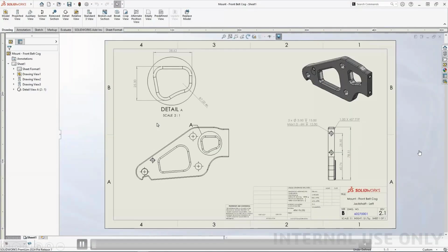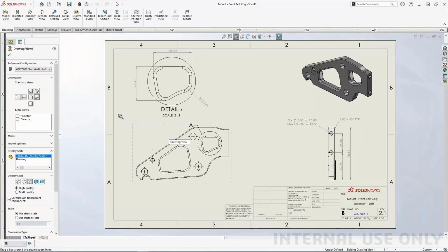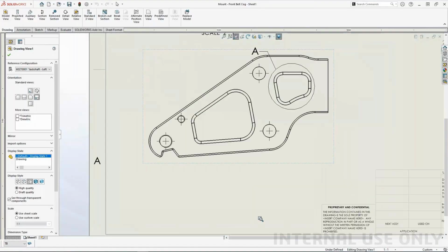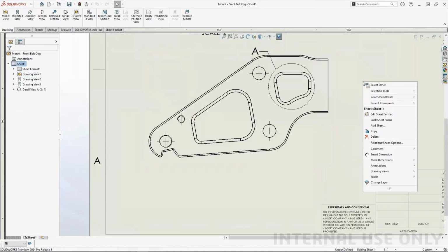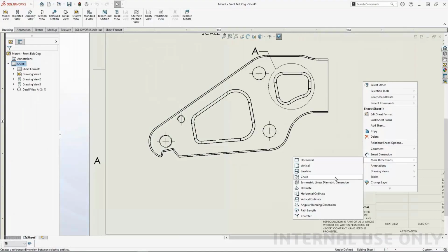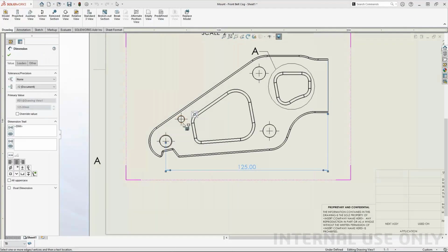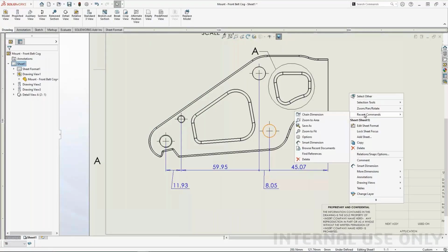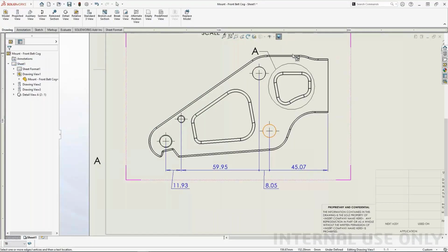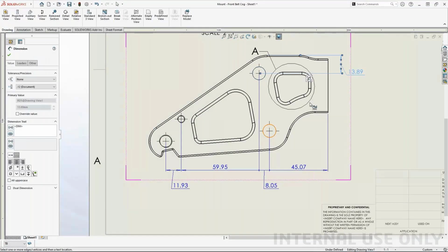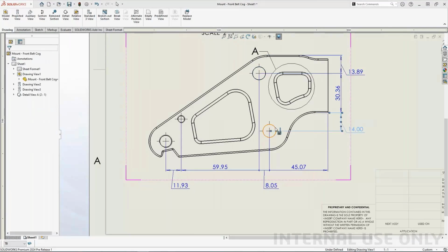So I just opened one drawing file where I created the different views. Now I want to give the dimension. In SOLIDWORKS software, we already have the chain dimension, baseline dimension. To define any particular component, I can select the chain dimension and select the edges accordingly. The chain dimension is applied. It is already available in the SOLIDWORKS software. Like this way, I can apply the chain dimension.